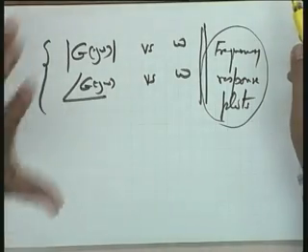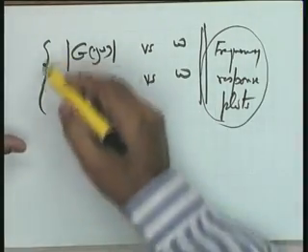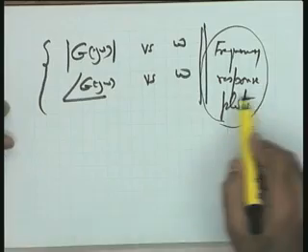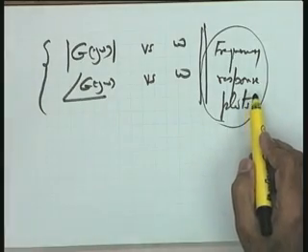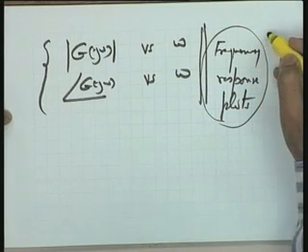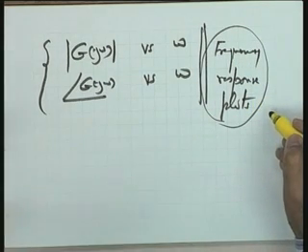Fortunately, the situation is not that. Actually, it is a complete characterization of the system, including the transient response, because given the frequency response, through Fourier transforms you can correlate this to the time response, and hence from the frequency response you can get the response of the system to any time function.